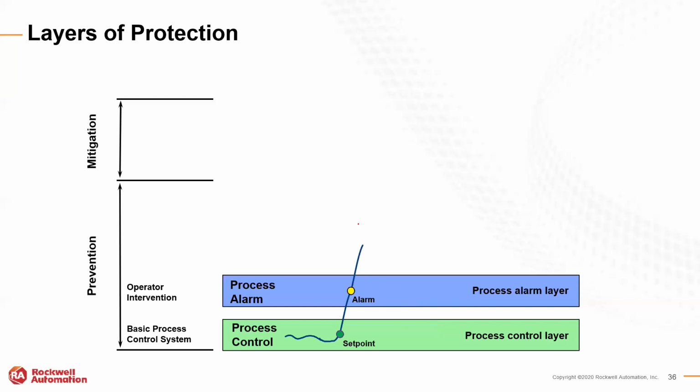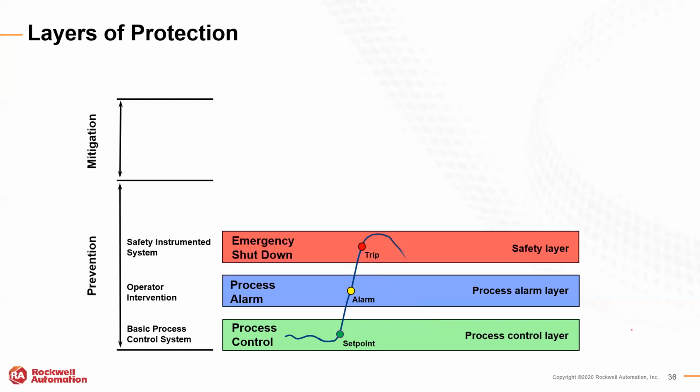Now, that doesn't work because maybe the valve isn't working or it's not tuned properly. So now the SIS has to come in and take action. Again, this is why the SIS must be an independent layer. Try not to use the same source of instrument error. Try not to use the same source of power. Try not to use the same valve, even. You can use diverse valve types, things like that. So there are ways you can try to really reduce the common cause issue.